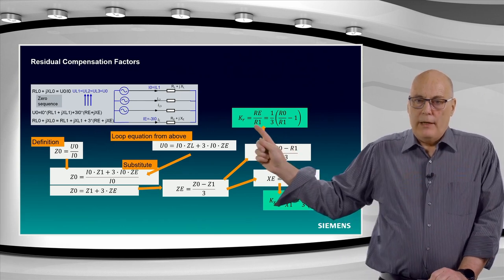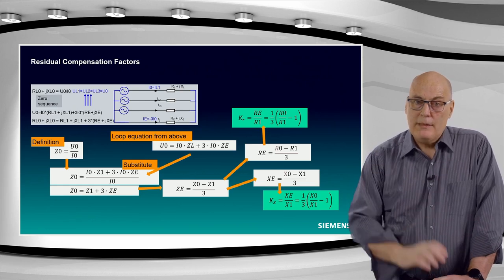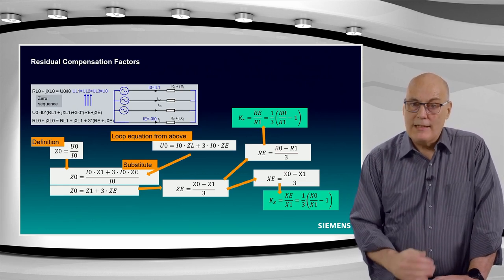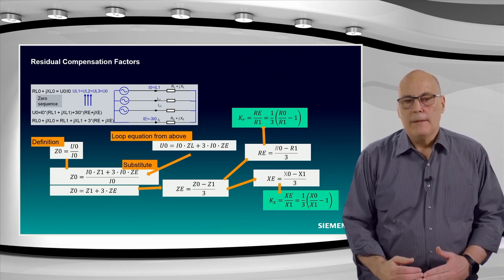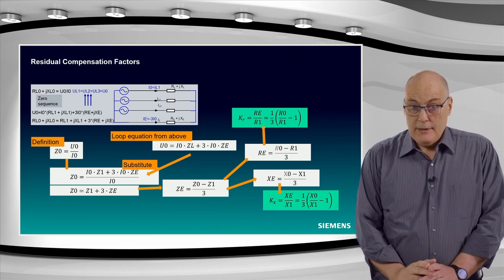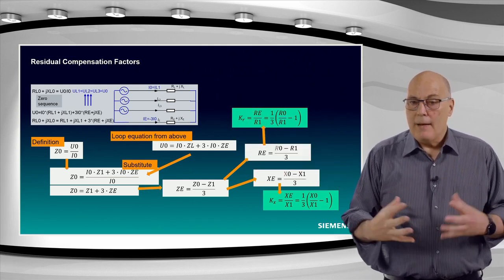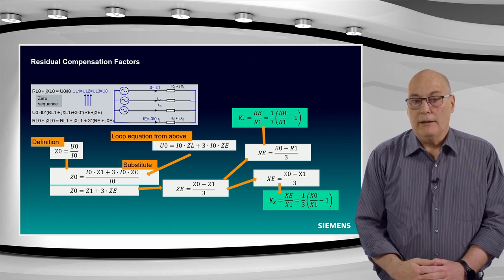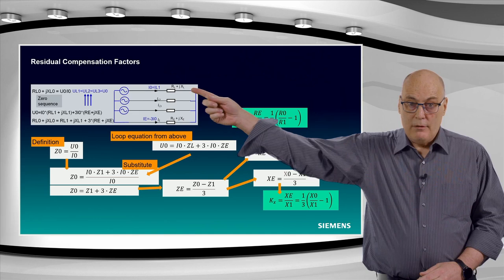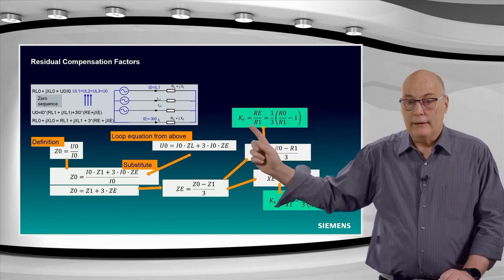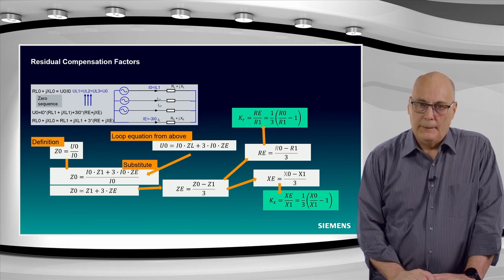Why can I replace R1 and RL? And you see it in the diagram here. You see that the impedance, as it is shown in the three phases there, is the ZL, which is RL plus JXL. That is your positive sequence impedance. For it to be a positive sequence impedance, that is our assumption, is that those three-phase impedances are exactly the same and balanced. That's the definition of a positive sequence impedance, and that then can be substituted directly. So we can replace that RL, XL, in this case exactly by the positive sequence R1 plus JX1, the definition.